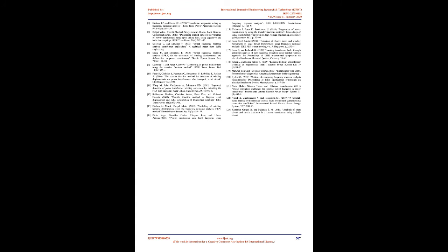The correlation coefficient and spectrum deviation were used to calculate the amount of agreement or disagreement between the two sets of faulty and normal measurements for quantitative explanation of the fault presence on the transformer windings. Spectrum deviation was found to be more effective than correlation coefficient in establishing the differences between the recordings of the SFRA measurements. V. Conclusions. Successful operation of SFRA method in precisely detecting interturn winding faults with a sensitivity of better